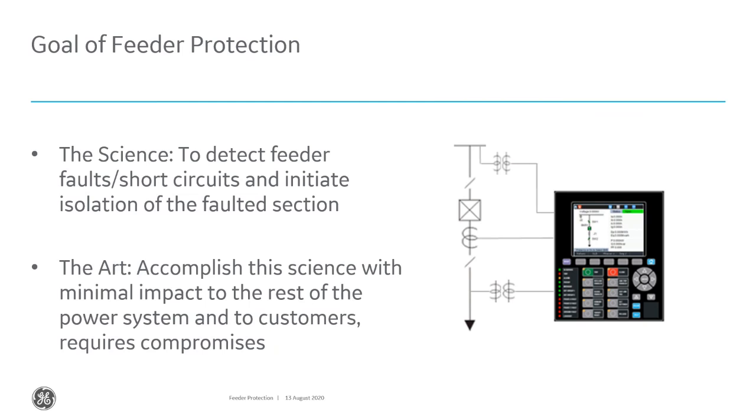For example, there's a piece of equipment that's very old, and if it's subjected to high short circuit currents for long periods of time, it's going to fail permanently. So you might want to set an instantaneous overcurrent element on that so that you trip as soon as possible. An instantaneous overcurrent element, we'll talk about, is an overcurrent element without any intentional time delay on it.